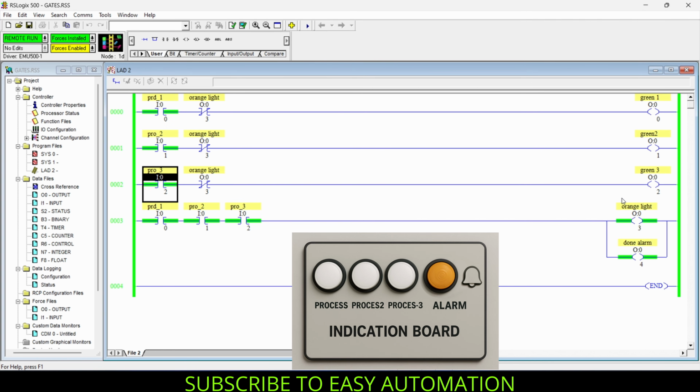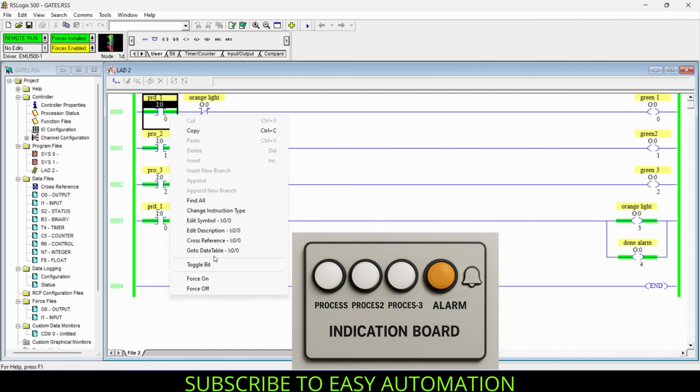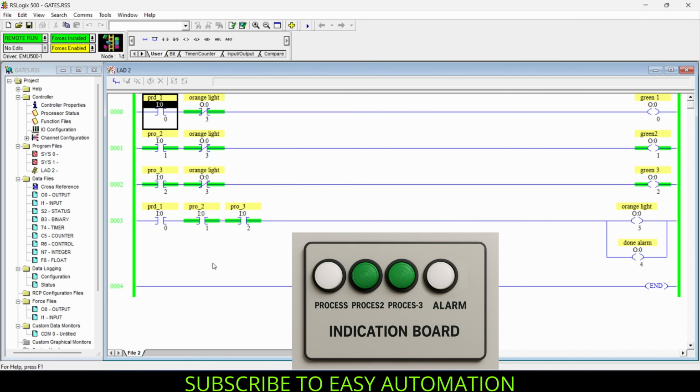But if you want to turn on this green light, we just need to untoggle our first process, then our green 2 and green 3 lights are on, because the supply to our orange light has broken here at process 1. So that's why these NC contacts are idle here. That means they are not operating and not cutting off the supply to our green lights.